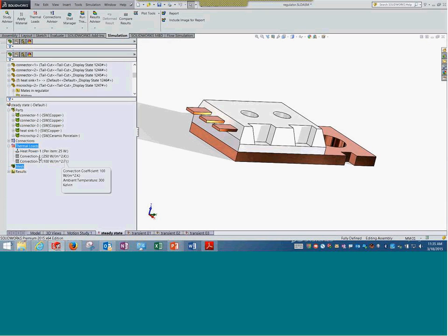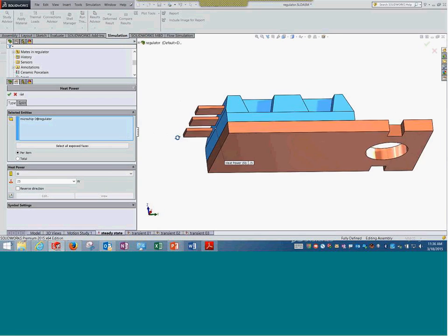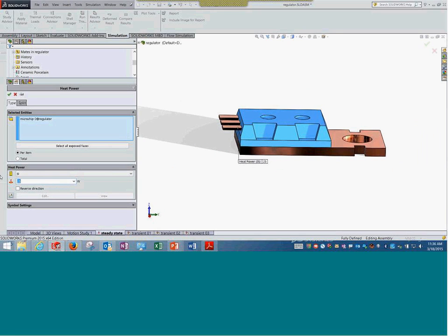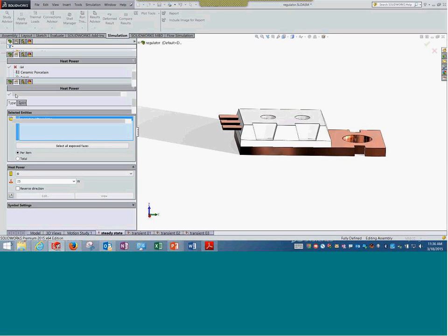So let me go back to this example. So one is heat power here. We are seeing this particular microchip is creating a certain amount of heat, which is 25 watts. And remember, during thermal analysis, even though users know that the heat is created by the body, we sometimes make the mistake of applying the heat power on surfaces, which is not realistic. So ensure selecting the right bodies or entities for application of things like heat power.